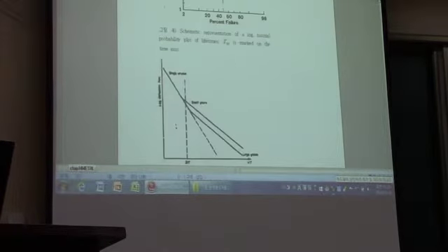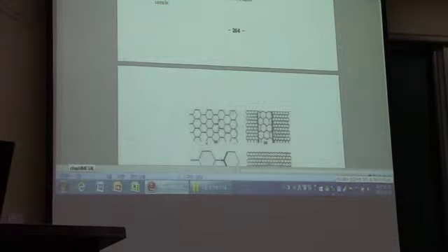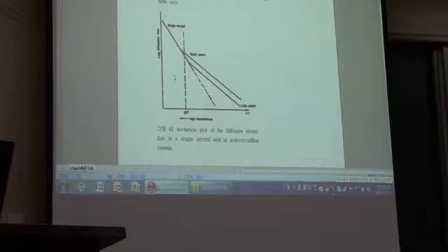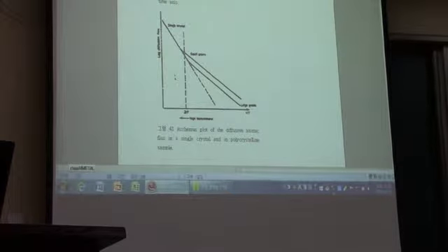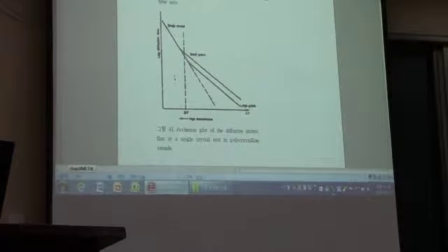This electron migration really happens along the grain boundaries as well. The ions move with the electron wind, and those ions will find their road on the grain boundaries. So grain boundary is affecting the electron migration phenomenon.